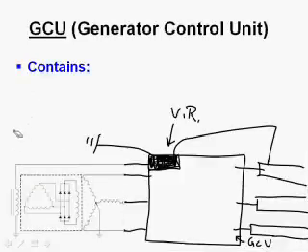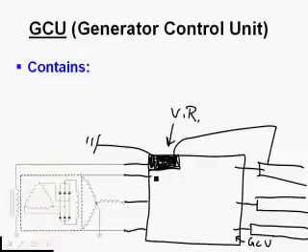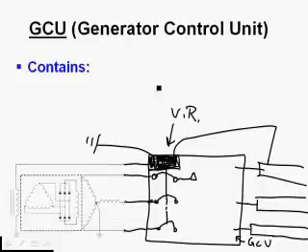Okay, let's see how many of these I can remember. All right, we've got the power coming out of the generator. We're going to run these through circuit breakers. And we're going to connect them so they all pop together or they don't pop together. So if any one of these output windings, if the amps in any one of them goes high, it'll pull all three circuit breakers simultaneously. So we're going to have a circuit breaker.